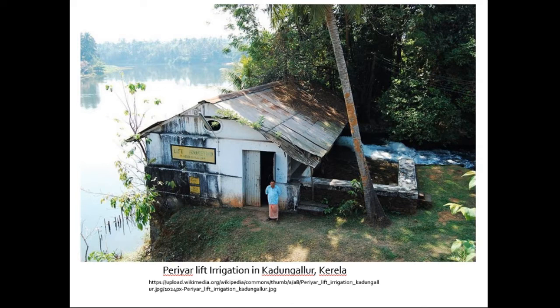The various advantages of lift irrigation systems are: farmers can apply water to their field according to the requirements, and hence there is no possibility of over irrigation. Likewise, the water table is lowered when the water is lifted from the well, thereby reducing chances of waterlogging. Similarly, as the water is supplied directly to the fields, there is no water loss due to conveyance.